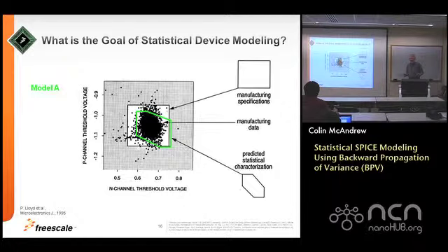So we actually used to have 2 separate models for the process. One of them was model A, which was the analog model, and one of them was model D, the digital model. And those models never exactly agreed because obviously they were different. So when we extracted those parameters for those models from the same data, we got different values for the particular corner cases when we ran the simulations. And every month we had a meeting between modelling, technology development, manufacturing and circuit design, and would put up plots like these to understand that the models were representing the process correctly and the process was in control.